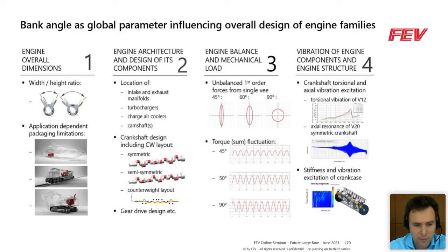from engine overall dimension, architecture of the components, engine balance and mechanical load, and then vibration. So we can overall rank these different criteria for importance. Also, for example, considering the number of cylinder variants that the final engine has to realize to define the best engine architecture that will fulfill the customer application.